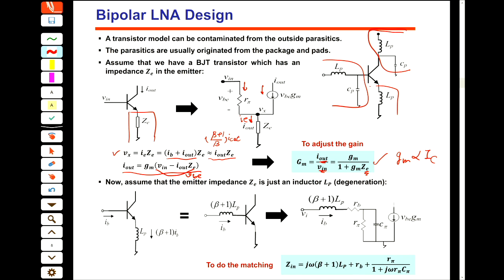It means that by changing the temperature, for example, you design an amplifier that works very well at 20 degrees, then you install it in a radar in the middle of nowhere, and it is 50 degrees, or minus 40 degrees. You assume that your amplifier gives you a gain of, I don't know, 15 dB, and then it gives you a gain of 12 dB.